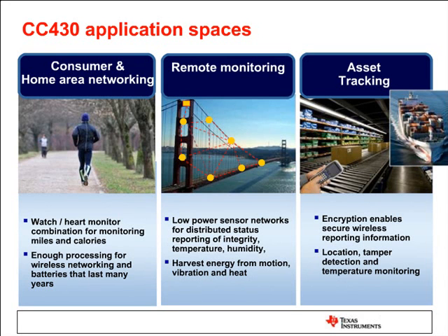Remote monitoring, in terms of sub-metering, communicating outside in the sub-1 gigahertz space can be very attractive because you can go longer distances, you don't have as much environmental noise in the network, and so any kind of remote monitoring and the ultra-low power is a key value proposition here for the MSP430 and the CC430, because let's say you have all these sensors on a bridge, you don't want to go crawl up there and actually have to replace the batteries, if you will.